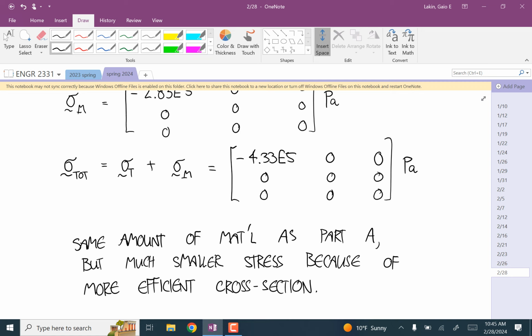In the X or the Z direction, would it be fine if you were to have it off center? You know what I mean? Yeah, so the way it works is for the bending moment, all that matters is the height. So anywhere horizontally along a line is the same stress. That's how it'll be for shear force too, but for torsion it'll be different.